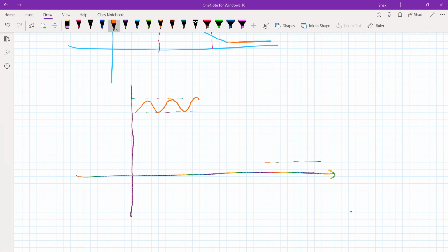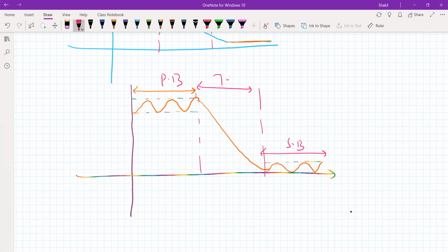This is the meaning of ripple, right? Can it do like this, right? All right. So this time we are allowing the ripple in both the pass band and the stop band, and the region between those two is the transition band. Right. Now, based on this, we'll have different types of filters.